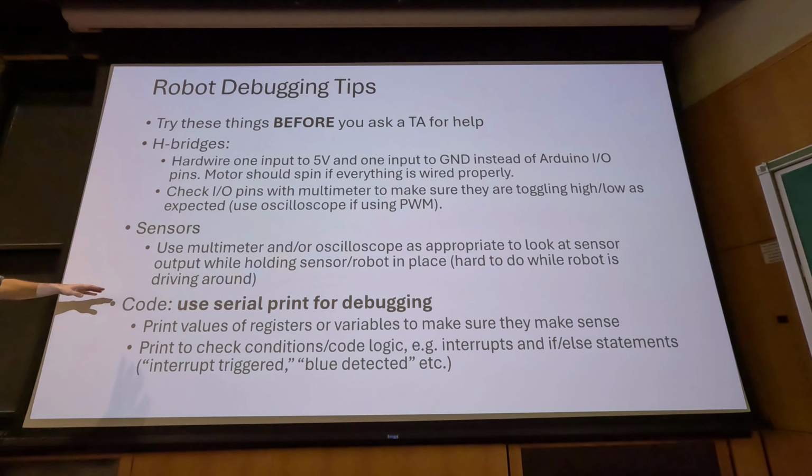You are going to be connecting these things using code, right? You are making the motors react to the sensors. So, in a basic example, if the robot is supposed to drive forward and stop when it sees a line, but it doesn't, all you observe initially is that the robot just drives off the edge. If your robot's driving forward, at least you know your H bridges are probably working, but did it drive off the edge because your sensors are not wired right, or they're wired right but too far from the ground, so the amount of reflected light isn't sufficient, or is there something wrong with your code? You don't know until you investigate all of these things.